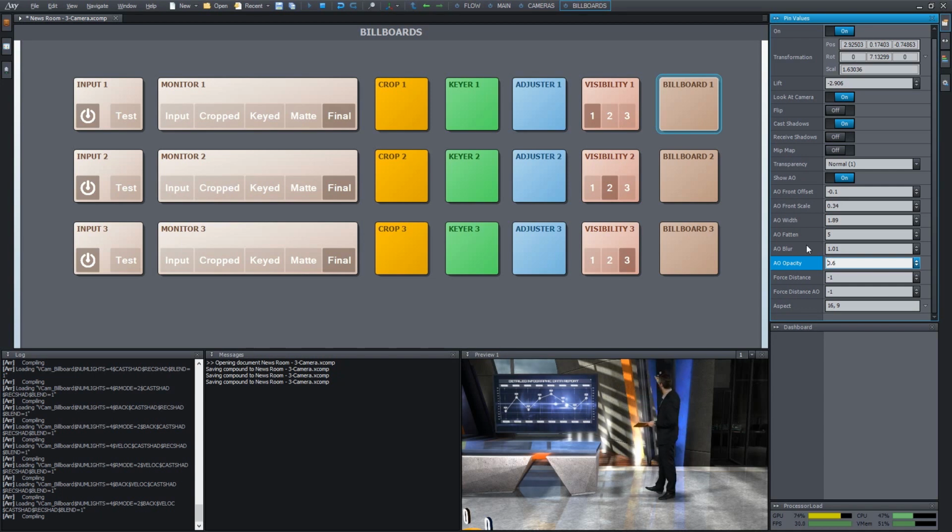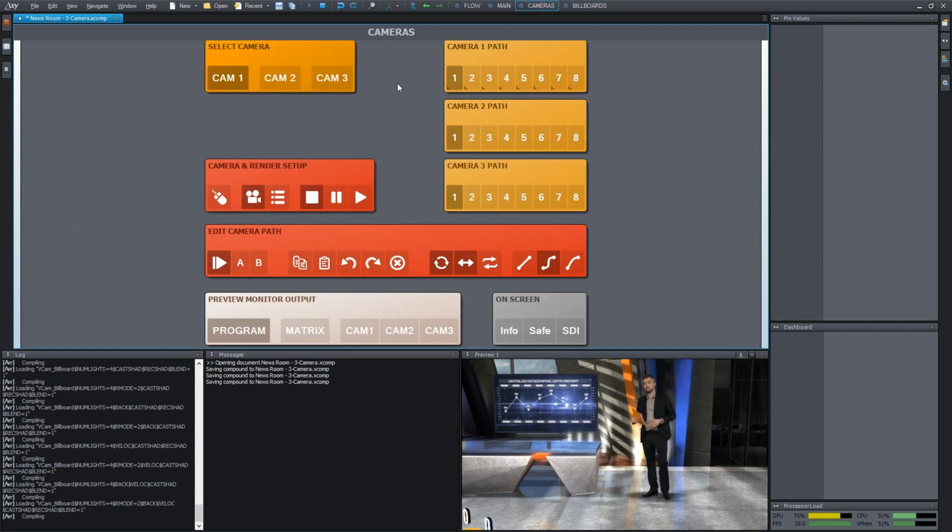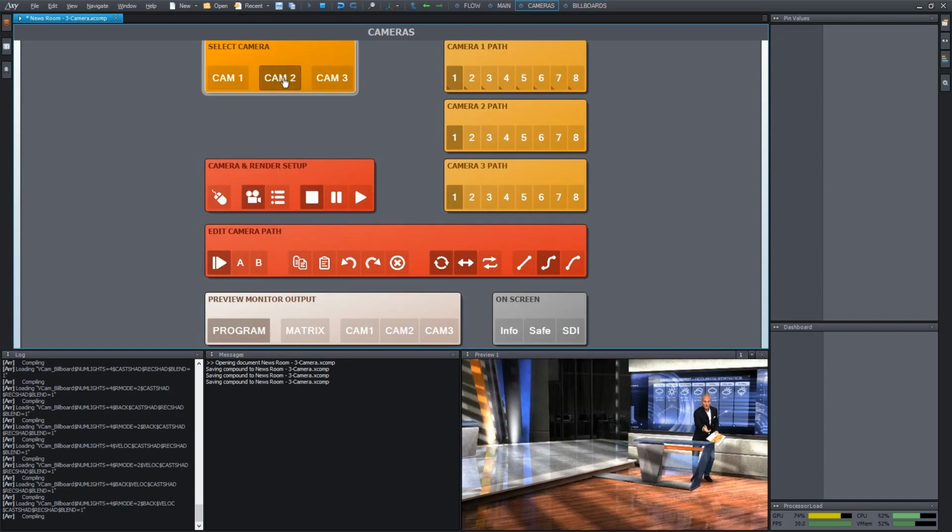The remaining parameters that I have not covered are tools for the graphical designer, and therefore these are not so relevant to us here. While adapting the same methodology, we have to repeat this process and go through the billboard settings belonging to the next two cameras as well. For instance, if we want to set the parameters of the second camera, we change the Select Camera box to the second virtual camera, Cam 2, and continue with selecting the same phases as earlier.